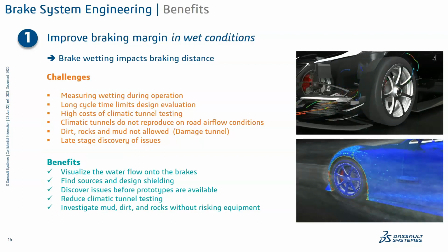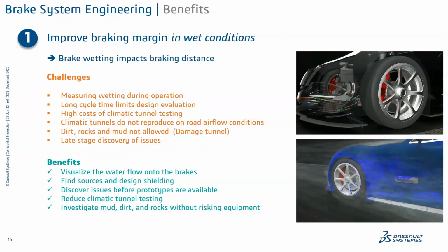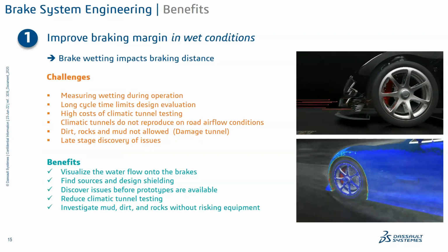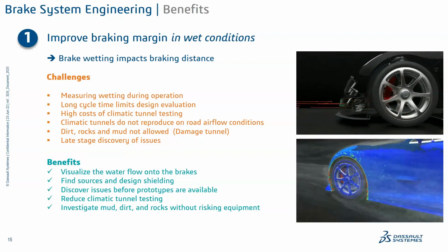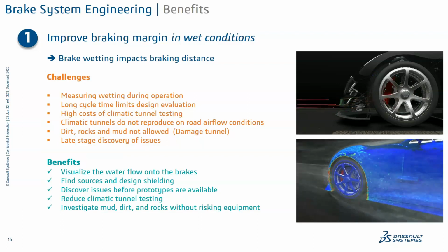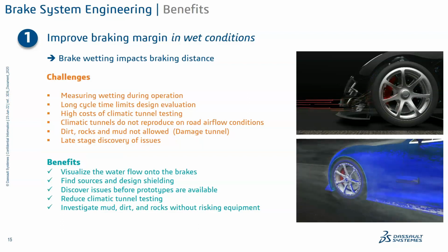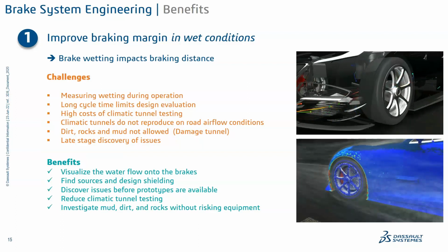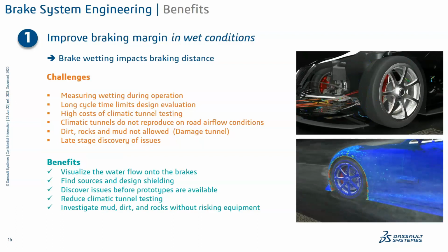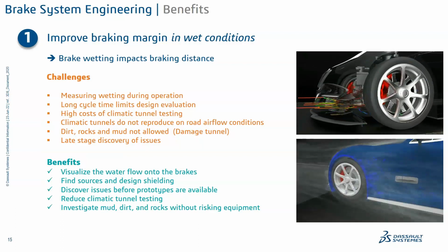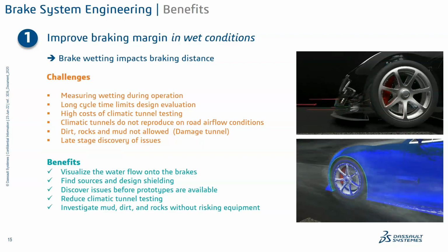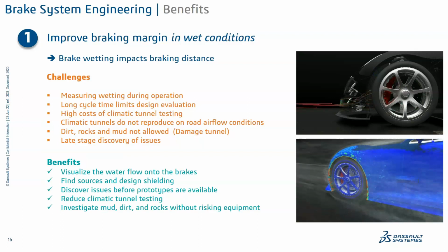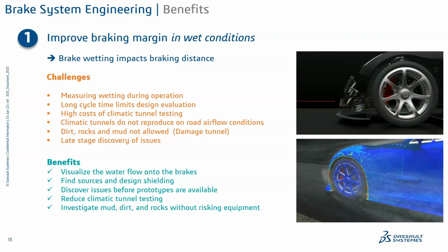So there are certain challenges, like measuring the wetting film, the thickness of the film during wet conditions during operations, and long cycle testing. Again, this limits your design evaluations. There is also the cost of testing: if you're doing tunnel testing or climatic tunnel testing, high costs are involved, and these tests do not reproduce your real world road conditions or airflow conditions.